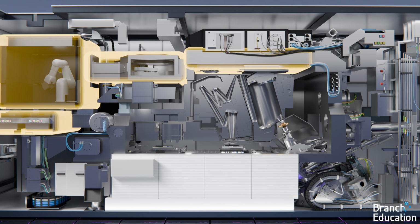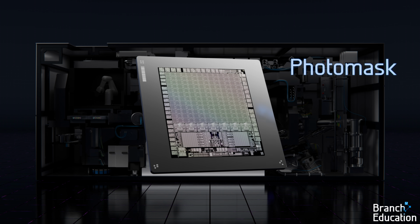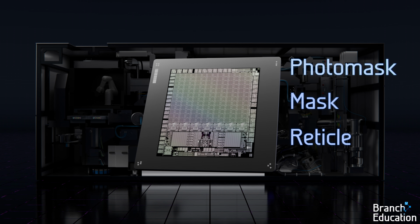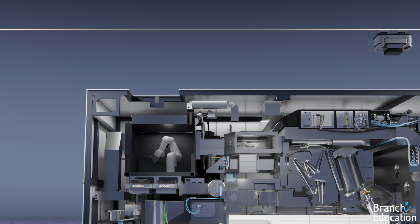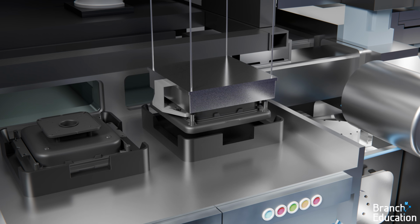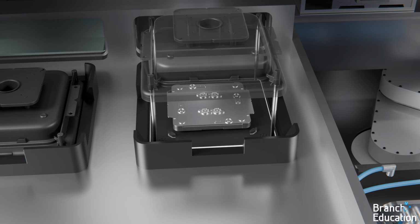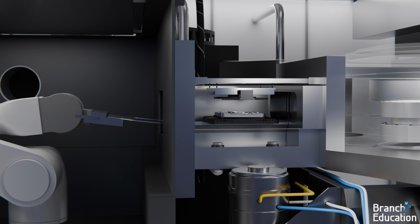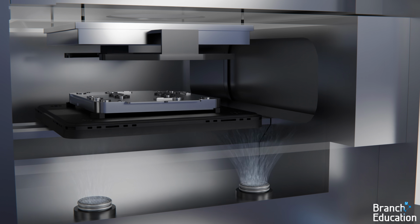Let's move on to the next part of this EUV lithography tool and explore the photomask, or mask, which is also called a reticle, and contains the entire design of a single layer of a microchip. The mask starts in a doubly sealed pod and is loaded onto the machine using an overhead transport system. The outer protective carrier is opened, and a robotic arm picks up the inner pod and carries it to a vacuum load lock. The chamber is sealed and pumped down to a vacuum, and the inner door opens.